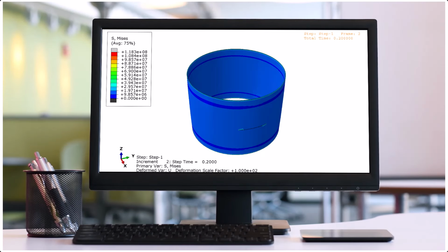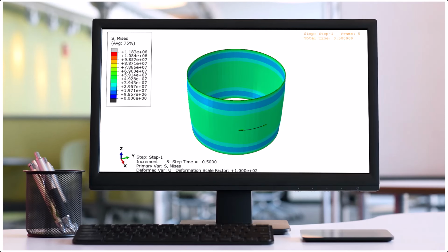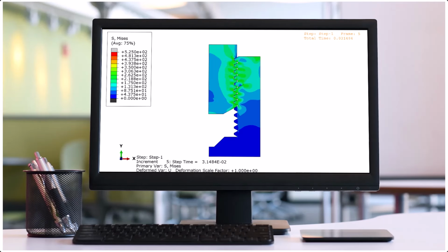In the next workshop, we tackle a more complex problem, using XFEM in Abaqus to simulate crack growth in a 3D steel tube model. In Workshop 5, we use the XFEM model in Abaqus to examine crack growth in a bolt connection. This is considered a notable and relatively complex simulation problem. It should be noted that to simplify the model, the simulation is performed in 2 dimensions, 2D.